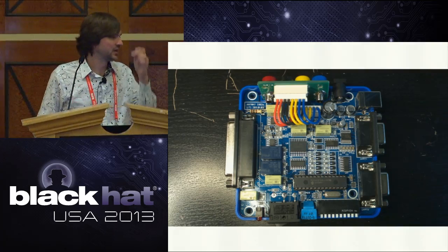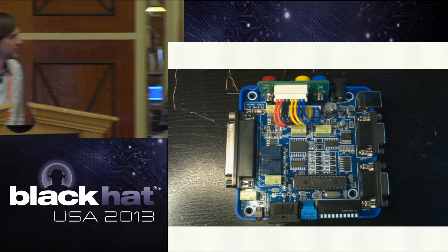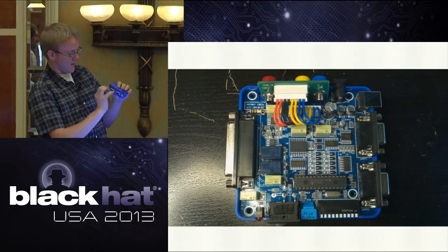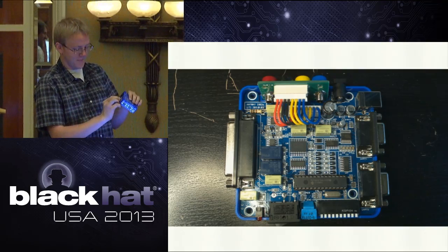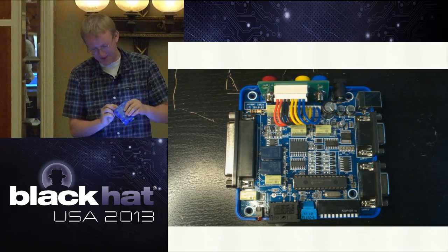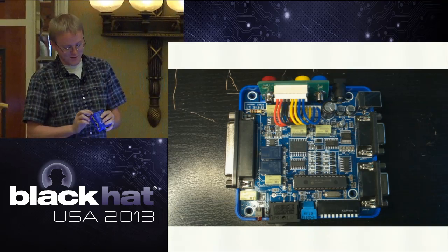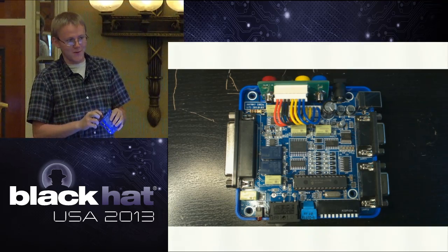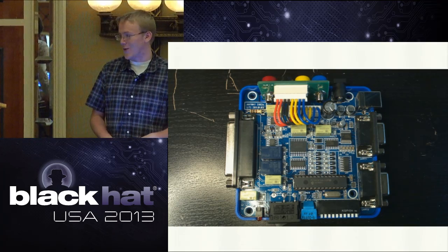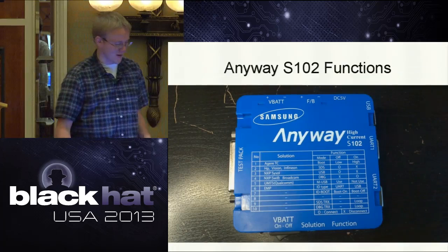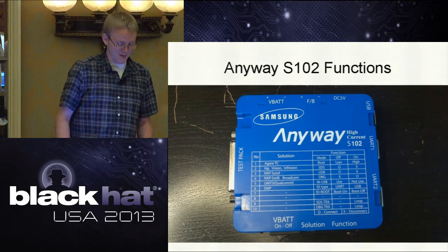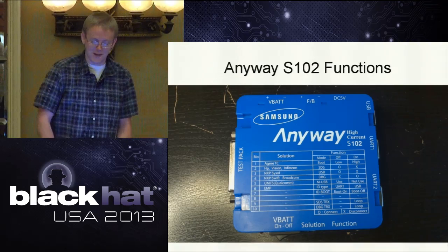And the annoying thing is, because it's not documented, you sit there and go, all right, solution 1, dip switch 1, nothing happened. Number 2, nothing happened. Number 3, nothing happened. And you can also combine them, so you can have number 3 and number 7, and it takes forever. It's way easier just to have a 150 resistor sitting around and do it that way.